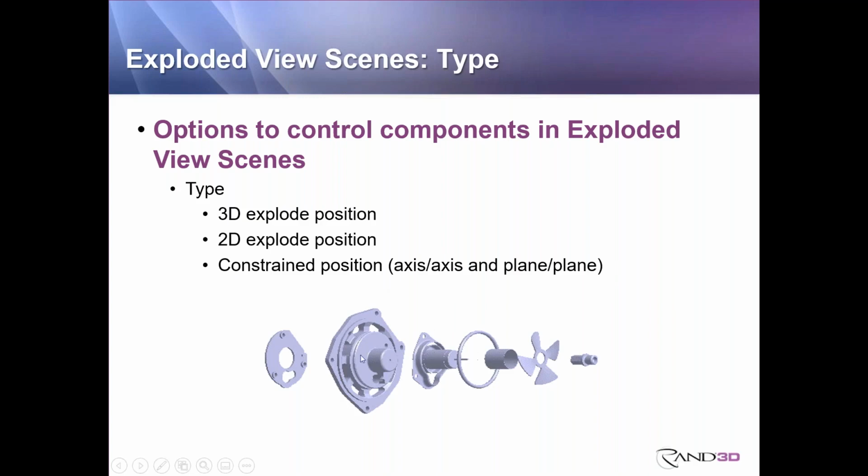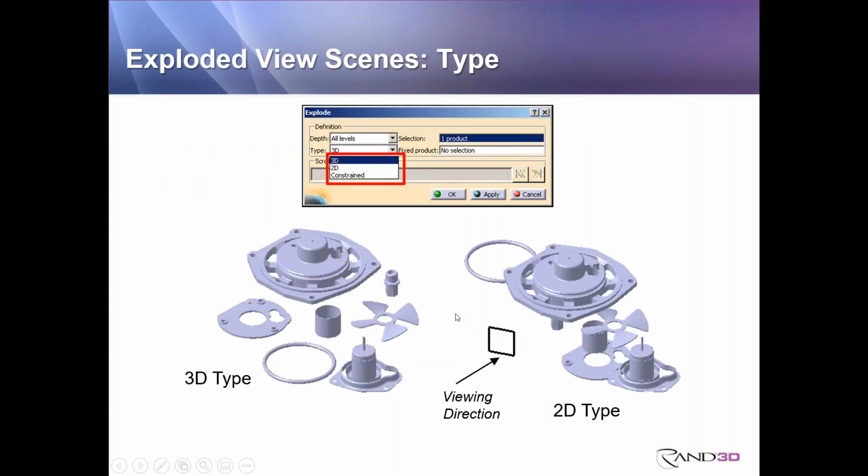Now here's what I was actually looking for in the assembly. If I had lined up all of my curved surfaces to be coincident to the next curved surface and line up with the main axis, you'll see it explode in a more traditional way than what you're seeing in my demonstration. But I'll also show you how, even if it does kind of fall apart on you, you can use your compass to help you get it exactly the way you'd want.